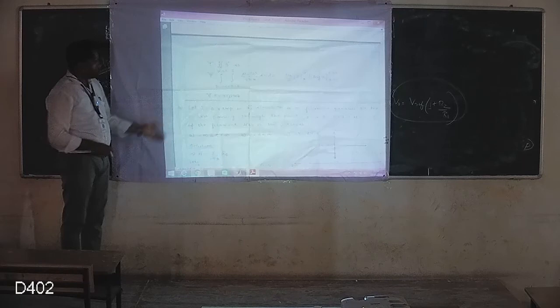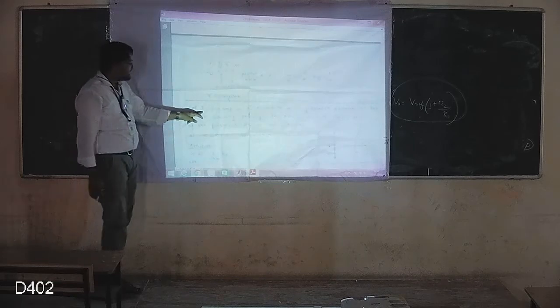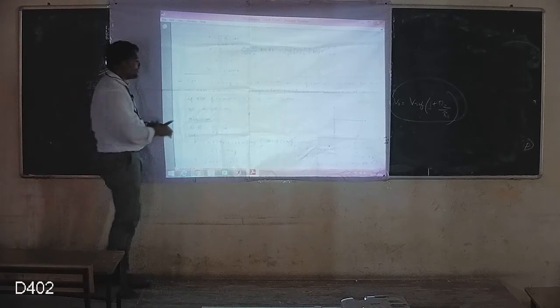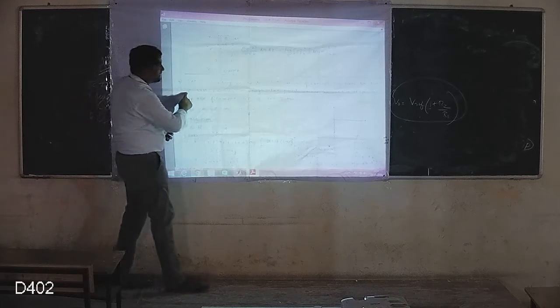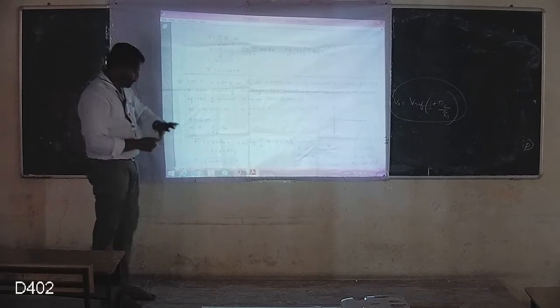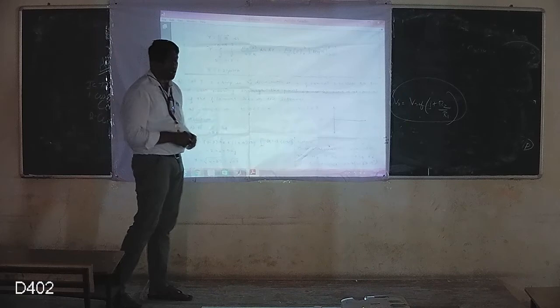And next, the fourth problem. The fourth problem is the case of a straight conductor, a finite conductor. Here the current is given as 0.4 ampere in the z direction. A point in the conductor is defined, which is 2 comma minus 4 comma 0. We have to find H vector at 0 comma 1 comma 0.